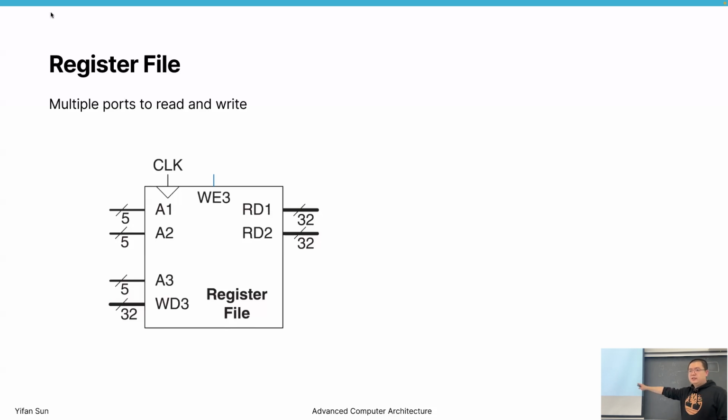So this is how a microarchitecture is designed. Microarchitecture determines how our circuits are designed. Now when we say architecture or instruction set architecture, it depends on what our instructions look like. If most of our instructions look this way, we have two reads and 1 write. But if some instructions have a carry bit, right? For a comparison, well, comparison is probably okay. For some instructions, we have 2 in, 2 out.